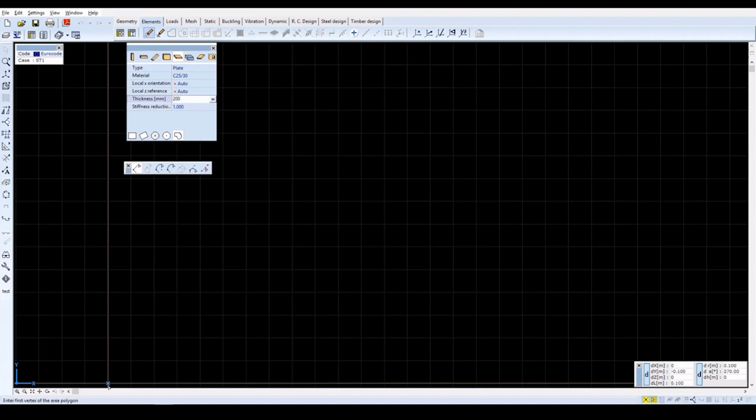Define the first coordinate by setting x equals 0, y equals 0, and z equals 0. Then press Enter. Define the next point by setting x equals 7.9, y equals 0, z equals 0, then press Enter. Now click on the Arc by 3 Points icon in the window and define the contour points by typing x equals 0.5, y equals 3.4, z equals 0, then press Enter, and again x equals 0, y equals 6.8, z equals 0, and then type Enter again.